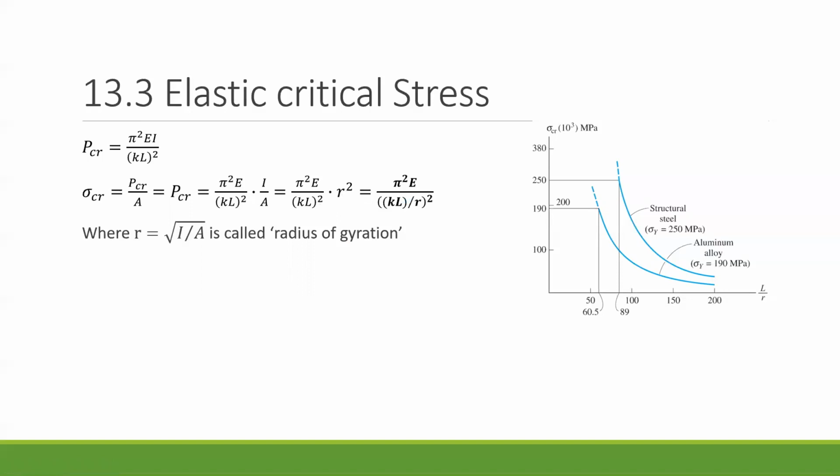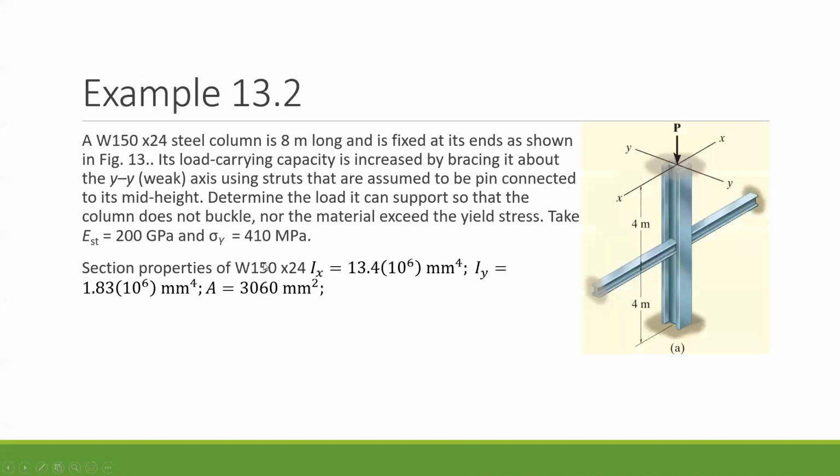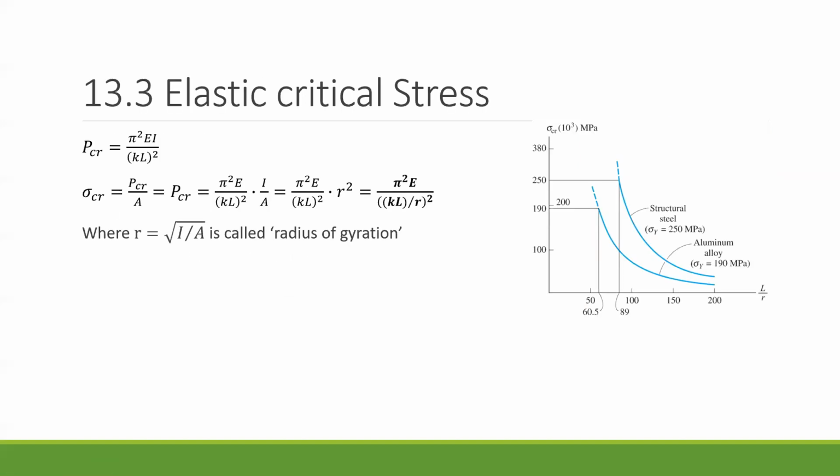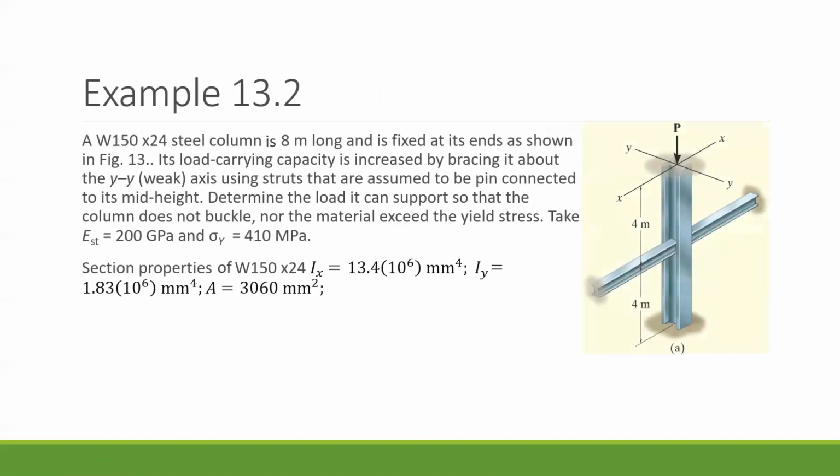You will see the definition of it, which we could also symbolize as lambda. Why is it so important for us? In every steel design course, we are always comparing buckling types by using this term, K times L divided by r. So, okay, let's start the new example.